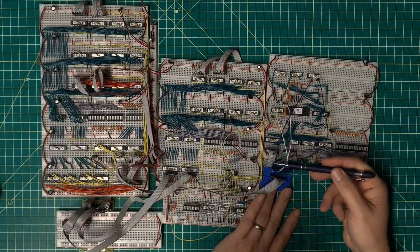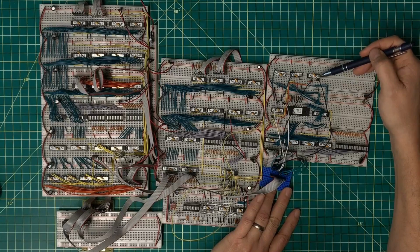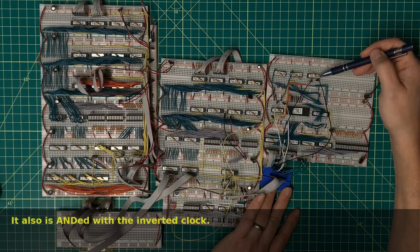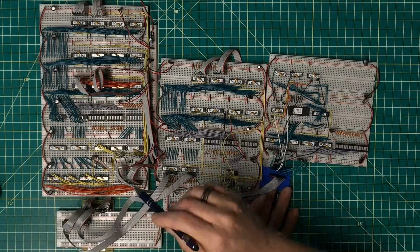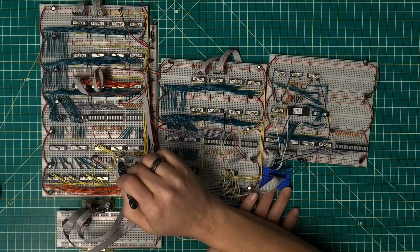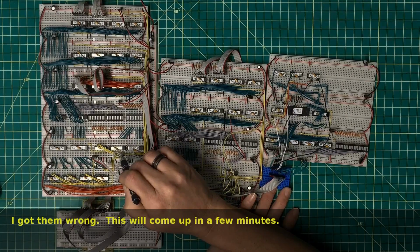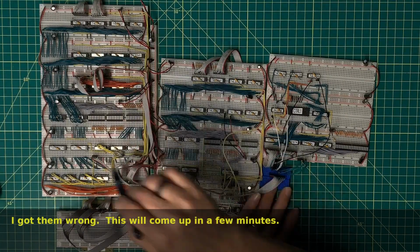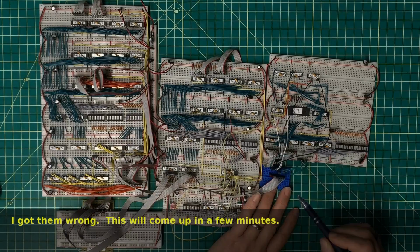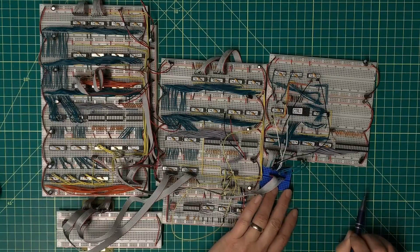So those would be these two black lines, which are coming off this 08, which the 74LS08 adds additional delay onto. Then I believe the next two in line over here become AND latch and address bus 1 assert, and then these 5 over here are the other 5 different buses that we're not playing with, so I've got those tied high down here so that they're not asserting as well.